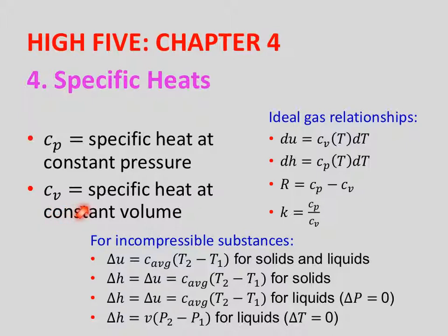The relationships are dU equals CV dT, and dH equals CP dT. R is CP minus CV. And then the constant k is CP over CV.